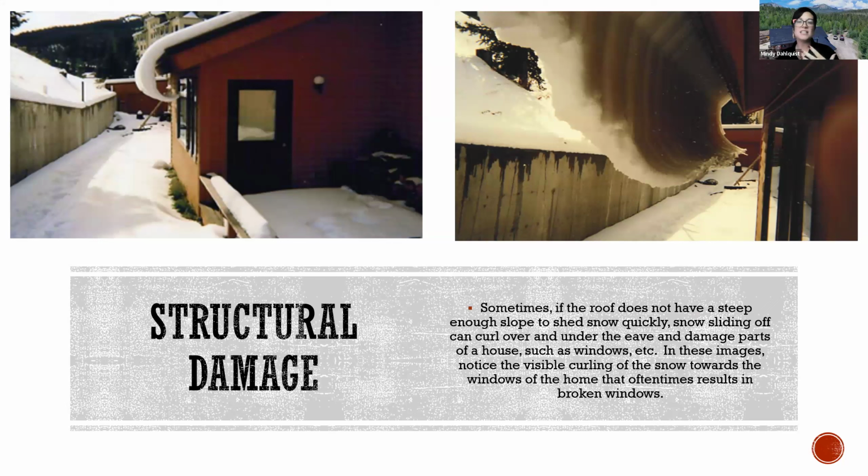Well, as it reaches the eave portion or the lowermost part of the roof, that is going to be much, much colder. There's a lot more airflow that's occurring, and so it is just a colder part of the roof surface. So with that, you not only have the start of ice damming and that creation with that temperature difference, but you also have gravity coming into play.